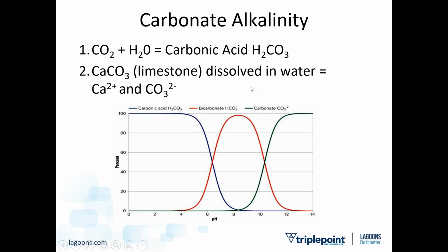HCO3 and CO3 also come from groundwater, from limestone. Calcium carbonate is CaCO3. When that dissolves in water, it tends to pick up another H, because if you're looking here in the neutral pH range we're dealing with, this carbonic acid wants to be HCO3, that it becomes the different forms only at the extreme ends of the pH scale. So HCO3, it's coming from the air, it's coming from groundwater. This is your biggest component of alkalinity. It's going to resist changing into this other form as the water becomes more acidic.